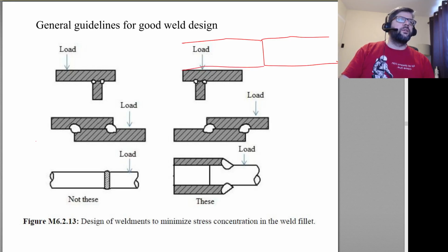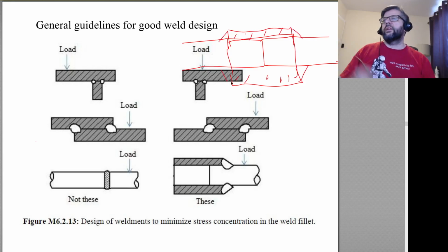then what you can do is just throw a sleeve on over top, and throw a fillet weld down in the corners there. And that'll do the trick too. Or basically, assume this pipe extends here, and then throw a weld down there too.